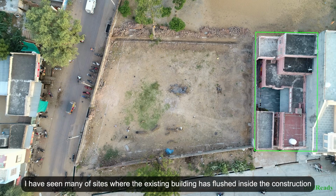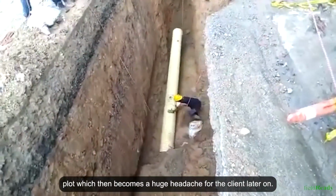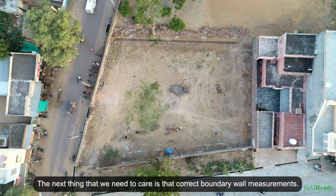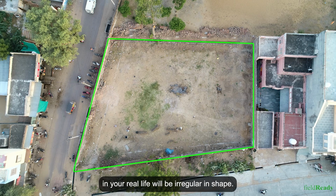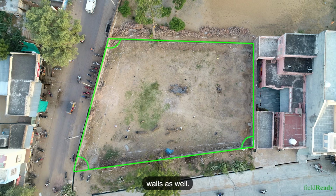I have seen many sites where the existing building has collapsed inside the construction plot, which then becomes a huge headache for the client later on. The next thing that we need to care about is correct boundary wall measurements. As we can see, this plot is irregular in shape. The majority of plots that you will encounter in real life will be irregular in shape. This means that with the measurement of wall length, we have to measure the angles between the walls as well.